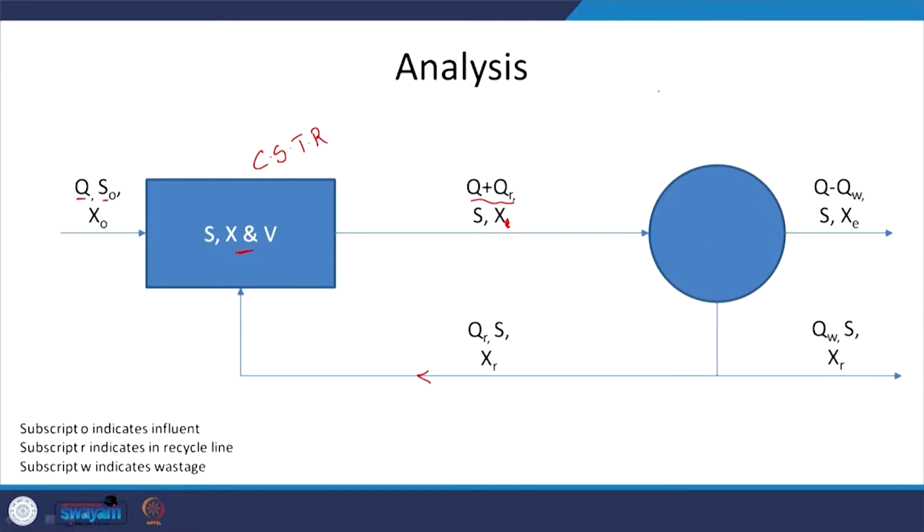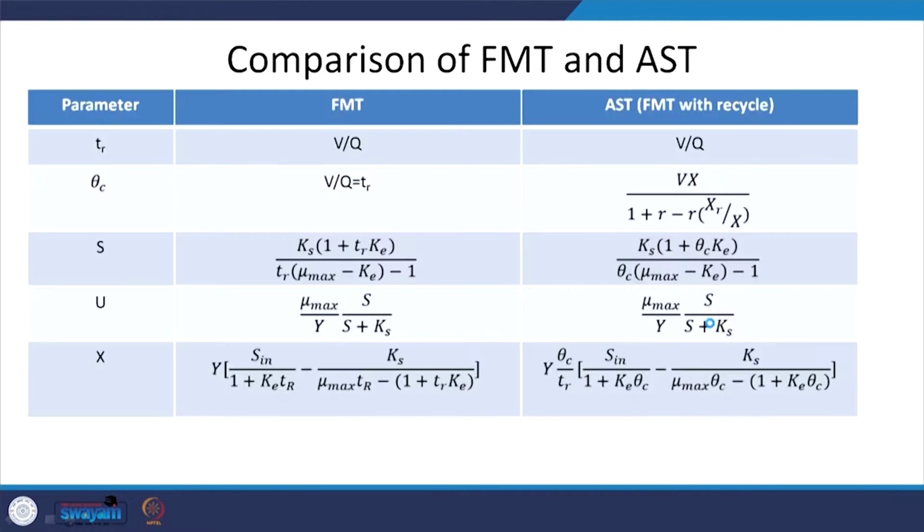And then we have the secondary clarifier or settling basin, wherein the flock forming microbes are going to obviously form flocks and then settle down. As they settle down, we will have clear water at the top, and that is going to be the effluent, and some of the sludge will have to be wasted. And we looked at different mass balances, as in we looked at the mass balance around the entire system. For calculating Q recycle and such, we looked at the mass balance around this particular system, as in the clarifier. We are done with that.